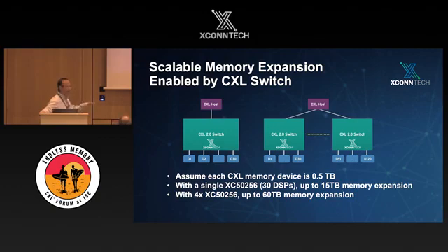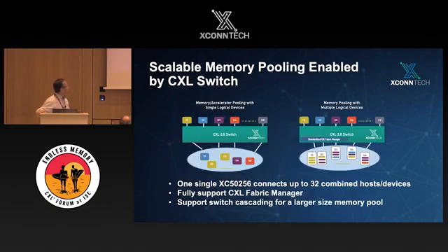In the today case, our switch virtualizes all the memory pool behind it, to be managed through a fabric manager, so that it can manage this big memory pool formed by SLD devices. But in the future, our switch also complies with the CXL 2.0 spec and is able to work immediately with MLD and the CXL 2.0 processors. Also some concepts are borrowed from CXL 3.0.